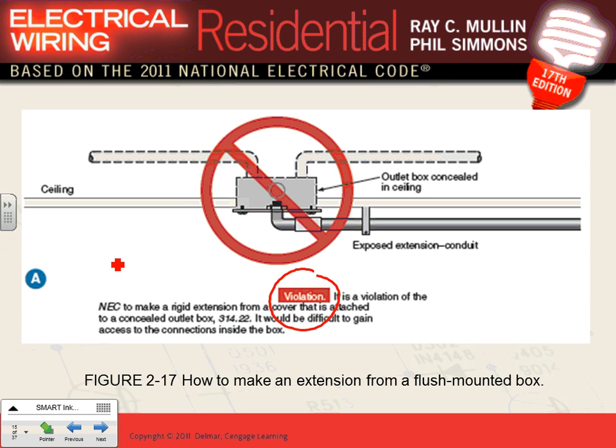By the way, from my own experience and from a lot of people's experience, most of the problems when you maintain an electrical box are at the termination. It's highly unlikely that something will happen to that wire inside that conduit. I mean, unless you drill right through it, that wire could live forever. It's highly likely that inside the box, as you pull power and you start putting, say, in this case, 20 amps, and you pull the 20 amps for a couple of hours, then you turn it off.